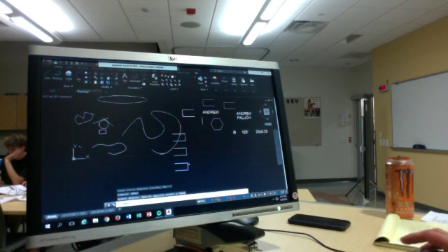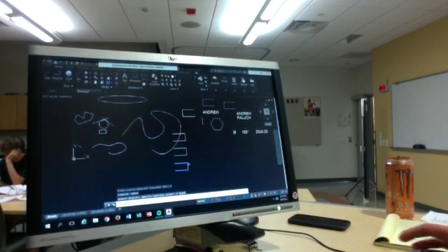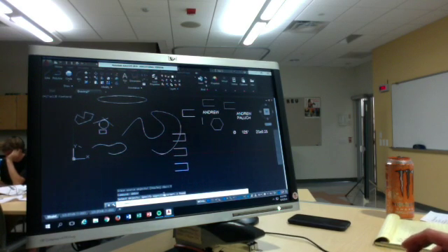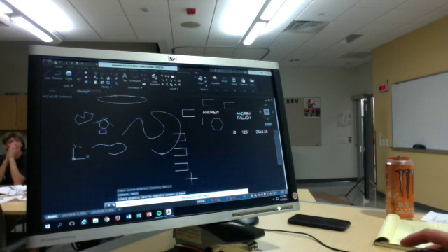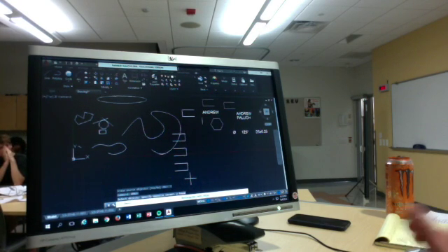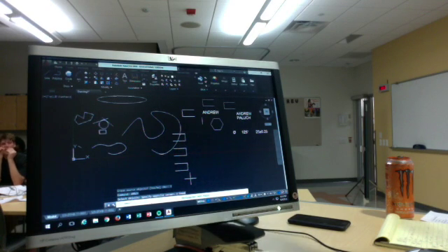So yeah, you can do a polar array. Choose your objects. What's cool with AutoCAD is that so much of it kind of walks you through each of the commands. So you choose your objects. It says that you have 3. You hit enter. Now that you have your objects, now it wants to know the array type. You can do rectangular, which is a pattern, x coordinate, y coordinate, or you can do a path array. You'd have to create a path first.